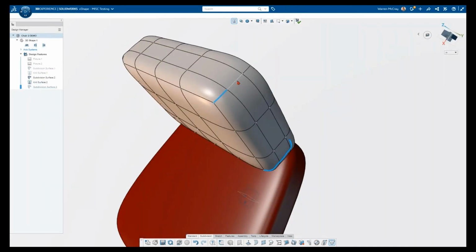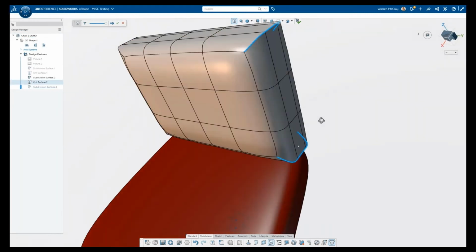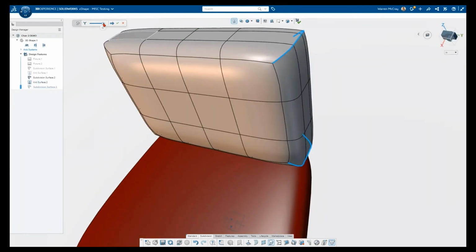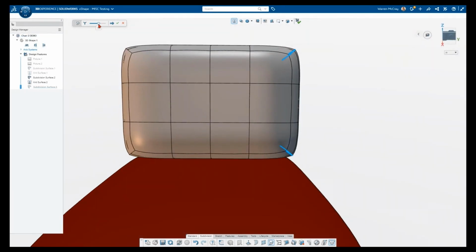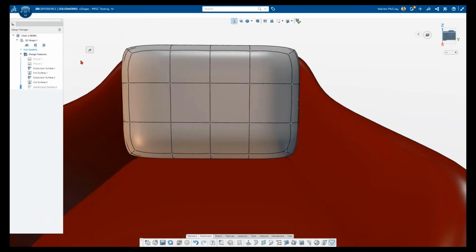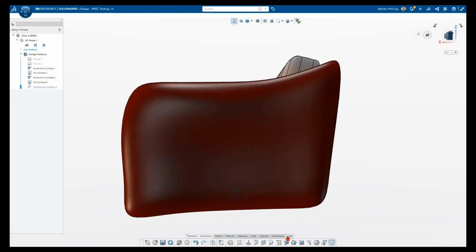So what I'm gonna do here, I'm gonna try to take these edges on the corner and just crease them using the crease edges command, just like we did before. Now I can adjust it so it's not too sharp. I've done it a couple times where I made it really sharp and it has a hard corner, and then I've done it where it's not so hard. And I don't want it too hard right now.